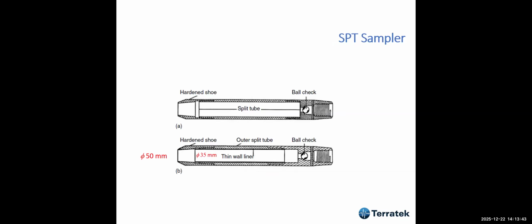So also we use a lot, in almost every project, drilling and sampling, and we have a variety of samplers which differ in the quality of the sample and the price, etc. Usually when we have very soft clays, we use tube samplers, okay? Soft to medium, tube sampler, Shelby tube. If we go into very hard soils, usually we use the Denison sampler. The SPT is always necessary, and we have, of course, rock samplers for when we enter rock.